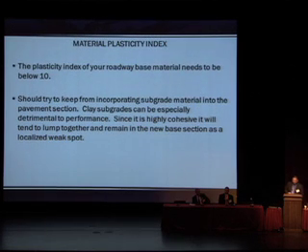The next thing you've got to look at is the PI of your materials. Some of our existing materials are old caliche bases, and of course some of those caliche bases have an allowable PI of up to 16, so you need to make sure that your existing materials are good candidates. Generally you want to stay with a PI less than 10. What happens is with the presence of clay, they tend to lump together, and these tend to remain in the new base section as localized weak spots.